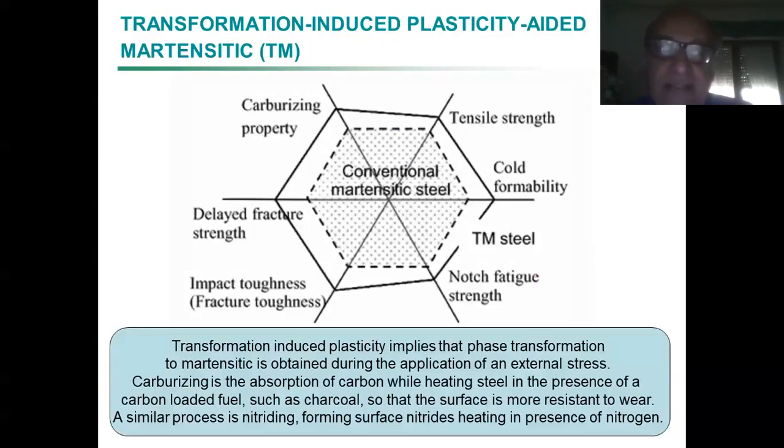As I was saying, for martensitic steel, like it is the case for shape memory alloys, you can induce plasticity by a transformation, or conversely, there is this exchange between mechanical deformation and thermal transformation, which is the same that happens in shape memory alloys, with the fact that here there is no reversibility, in the sense that you would need to change the structure.